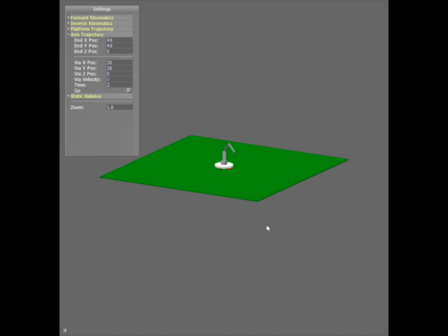Here we have the trajectory generation for the arm of the robot. This section generates a trajectory for the arm to move to any point in the 3D space around the platform. The length of the arm of the robot is 100 centimeters. Here we have set it to go to 20, 20 in the XY plane and then 40, 40 in the XY plane. If we extend our robot too far, we'll set this to 120 in X and 120 in Y, then the robot's platform will move to a closer location that will allow the robot arm to reach it.